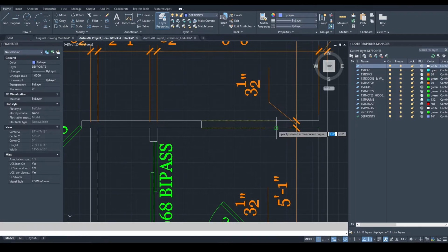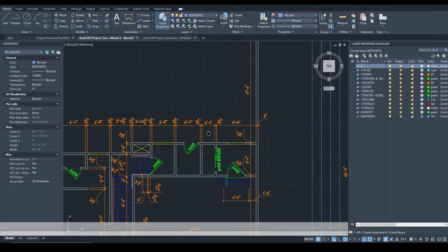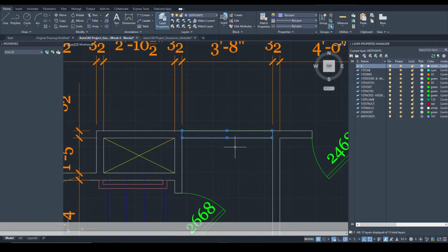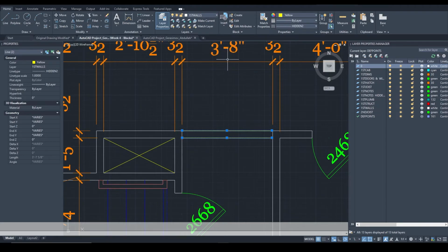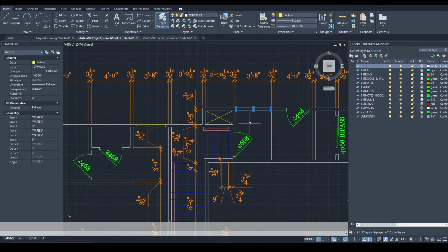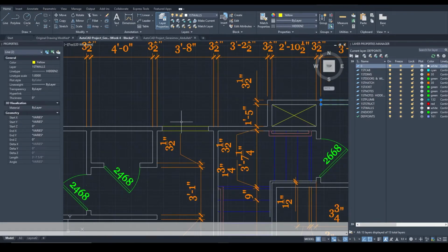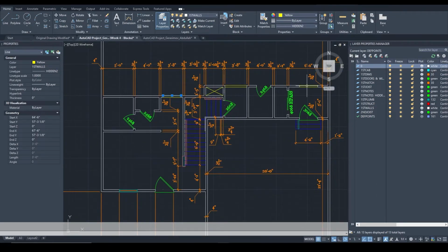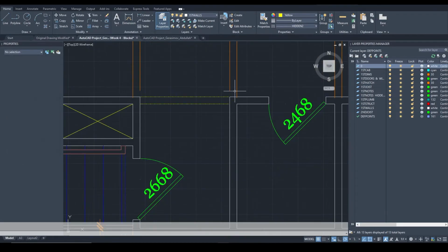is a 3-foot opening that is offset from the edge by 1.5 feet, or you can center it. It depends on your personal decision. Here, an entire portion of a wall, which is 3'8", is going to serve as a door opening. Here, only a 3-foot opening. Make sure you show them in the correct layer, first walls, and line type heading 2.